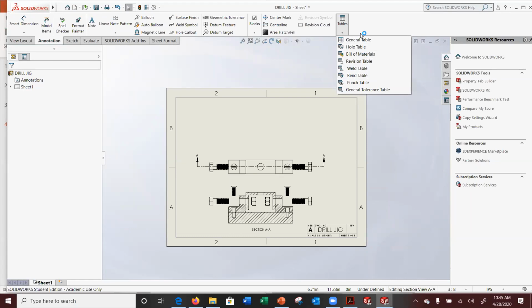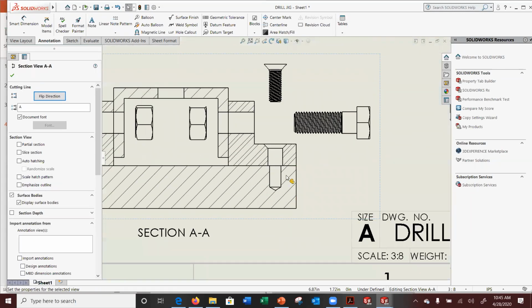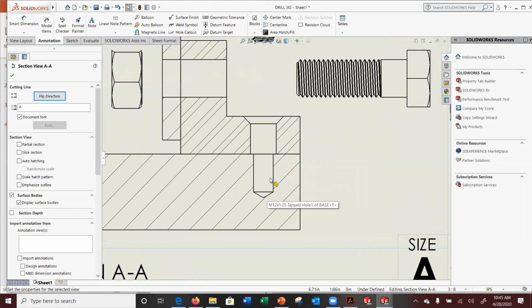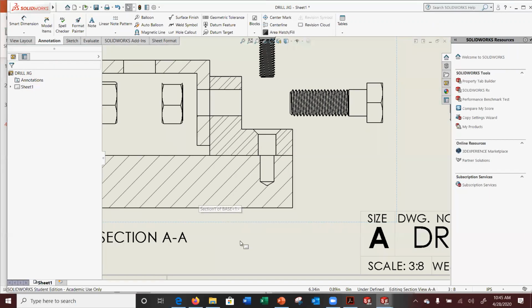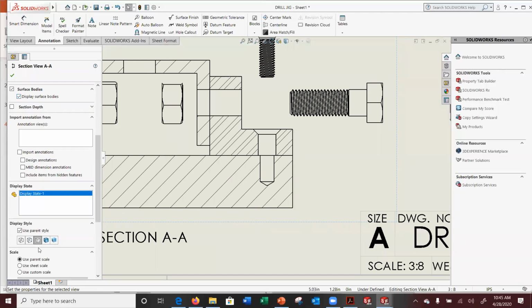Yes? You can see the top, the hole that is tapped. It will not show it as a tapped hole in the section in here as default settings, no. Okay. So over here, it doesn't show, I know that, which is annoying. At the part level, it'll show it if I didn't have it through. I think one other way I could do it is, nope, doesn't care.